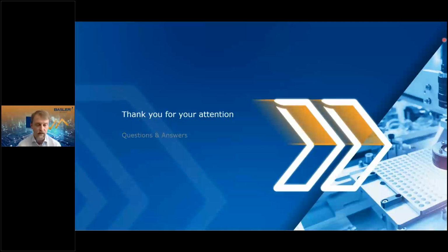You can also combine multiple cameras into a single process. Let's say we go for a stereo application and you would like to perform the rectification for both images coming synchronously into a system, then we have a single process where we connect 2 cameras, and then there is a single DMA transfer at the end forwarding all the data. But it's not only a single DMA transfer, we can use multiple of these, so that's possible. The parallelism itself, that was also a question.